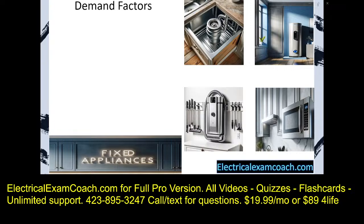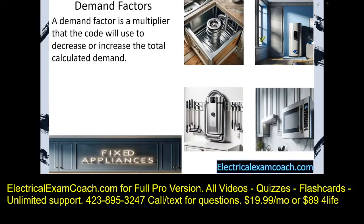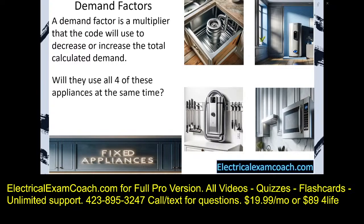Before we dive into the calculations, let's learn about demand factors. We're going to be using them for the rest of the program. A demand factor is a multiplier that the code will use to decrease or increase the total calculated demand. The question is, will they use all 4 of these appliances at the same time? And the answer is no. So the code makers have made it so we can reduce the overall demand. Instead of just counting them watt for watt, they've made some multipliers that allow us to reduce the demand that we calculate. And remember, if we have less amps, we could have a smaller service. If we have smaller service, we could have smaller pipe, smaller wire, and a smaller overall cost of the job.